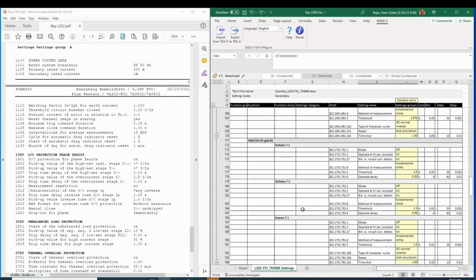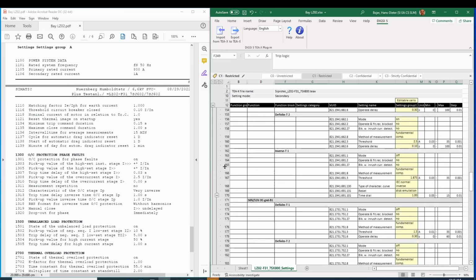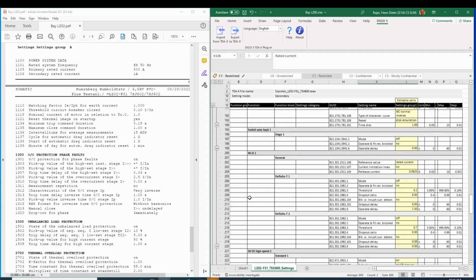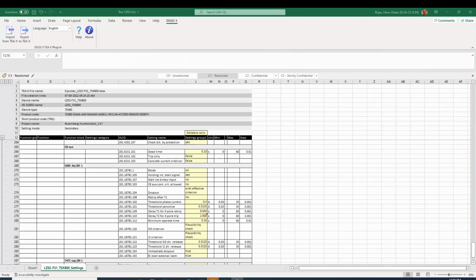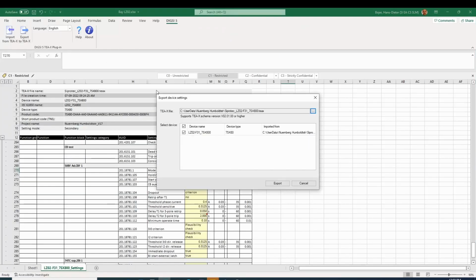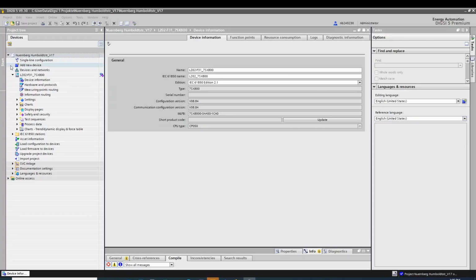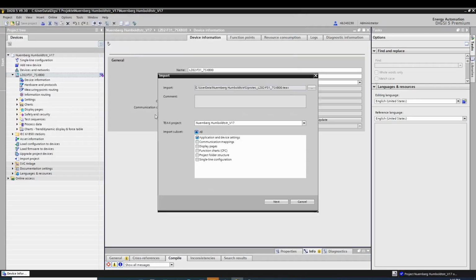For the correct parameter input, detailed expert knowledge of functions and algorithms of old and new equipment is required. Functions and setting instructions can be found in the respective device-related manuals. Further support is available via our hotline or from a Siemens contact person responsible for you. After completing the parameter input, save the data and perform a TX export. You now import the TX data of your new device into your DIGSI 5 project.